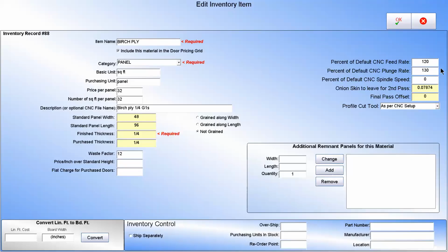The same tool is not going to go at 210, whatever it is, feet per second, meters per second, or meters per minute, or whatever. It's going to go at 120% of that. So 120% of 210, what is that? 42 plus 210 is 252 feet per second, for example.